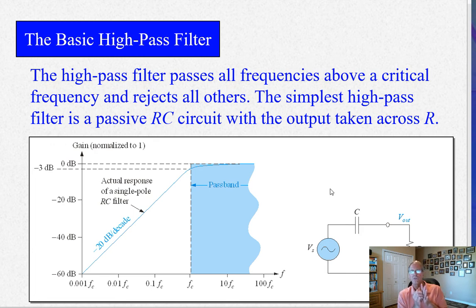And as we go through these filter circuits, I encourage you to do that if you want to figure out, because for most of us, it's probably pretty straightforward to see that this is a high pass filter, because you have a capacitor in series, right? Anytime you have a capacitor in series, it's always going to be a high pass situation. Sometimes, as we'll see in some of these circuits, maybe next week, where we have more capacitors in different places, it might not be as easy to determine whether it's high pass or low pass.